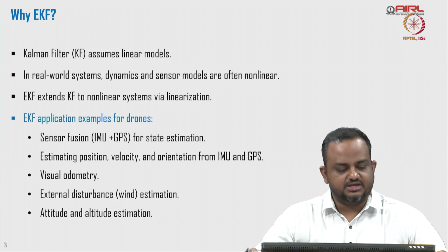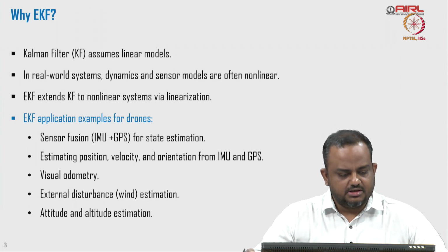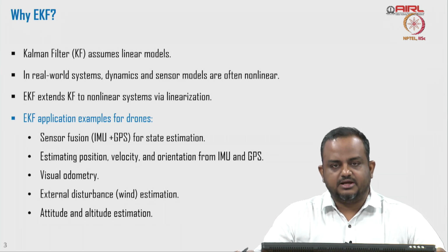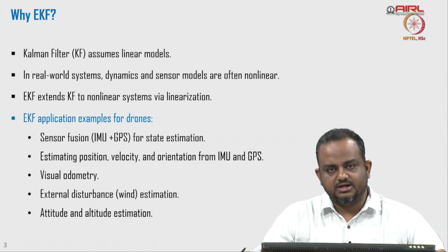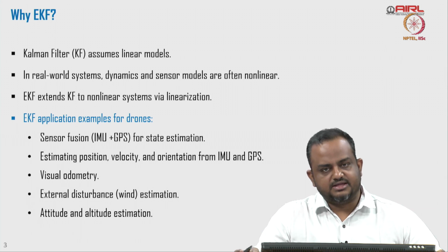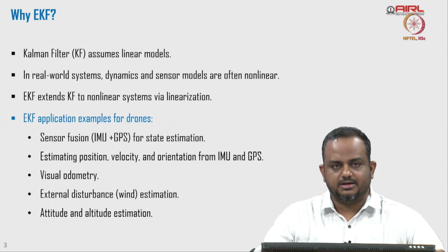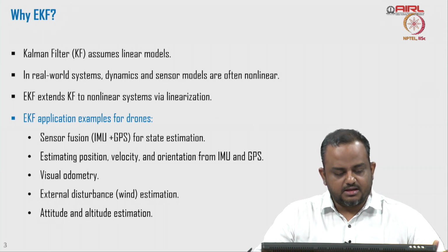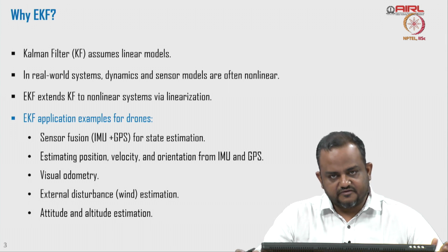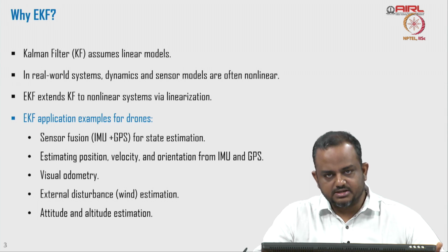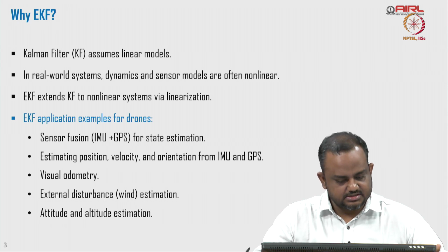So, what is EKF? What is extended Kalman filter? Kalman filter assumes linear models and Gaussian noise. In real world systems, the dynamics or sensor models are often nonlinear, which is very practical, and that is how we consider systems in our regular practical life. Then EKF is an extended version of Kalman filter which handles nonlinear systems via linearization. What is the meaning of linearization? How we linearize? That I will come to in later slides.